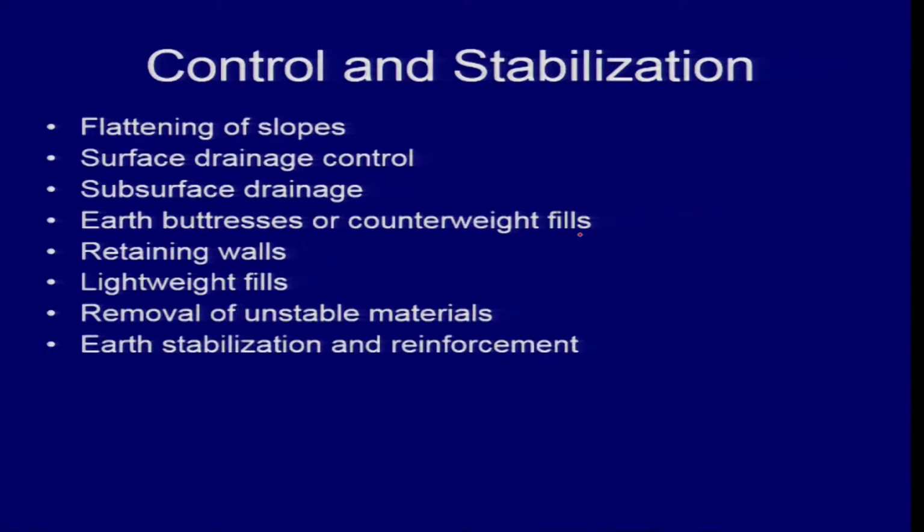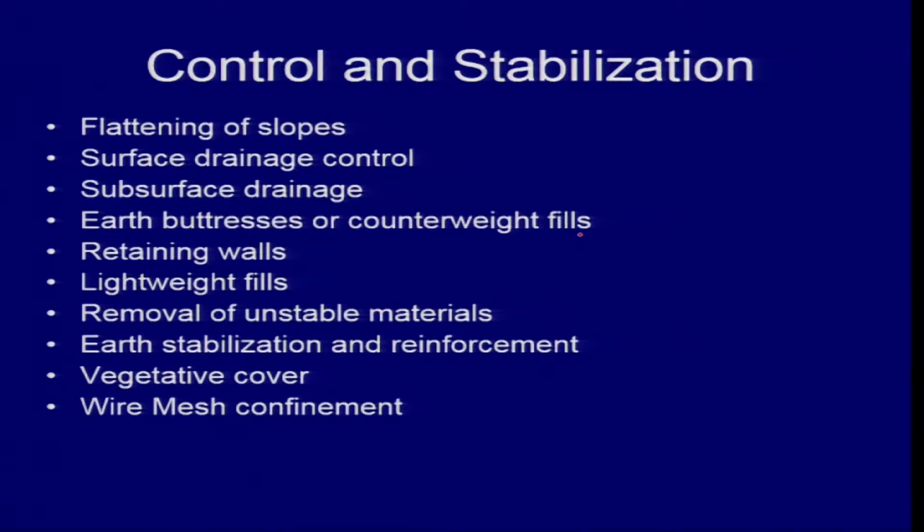Then earth stabilization and reinforcement. You can do vegetation cover, wire mesh confinement. This confinement can be used when you are having major rock falls in the areas. You can use that, or a combination of both. You can have the wire mesh, and then you can also do the reinforcement of the areas.